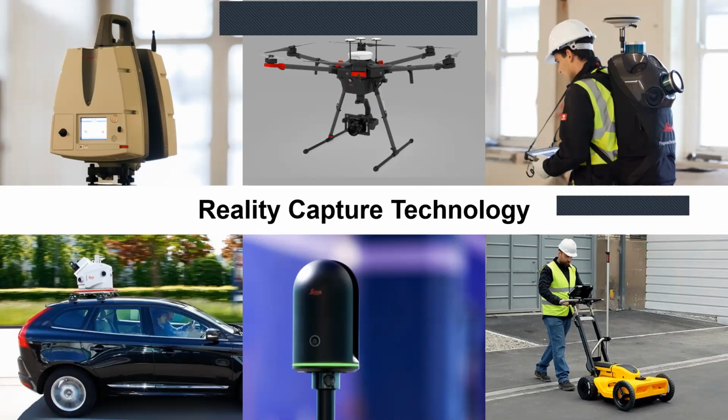Then there were a few requirements of construction, like if you are making a road, these scanners will take you forever to do a survey of 200 kilometers of road. In all those cases, vehicle mounted independent scanners were designed. Those were for mobile capturing, so that you can run at 40, 50, 80 or 100 kilometers per hour, and you can capture the data depending on the density you need. This was all about capturing something above the ground.